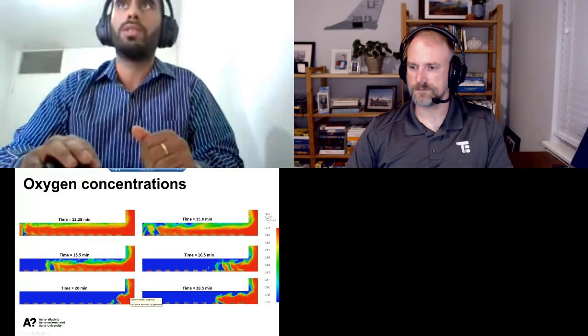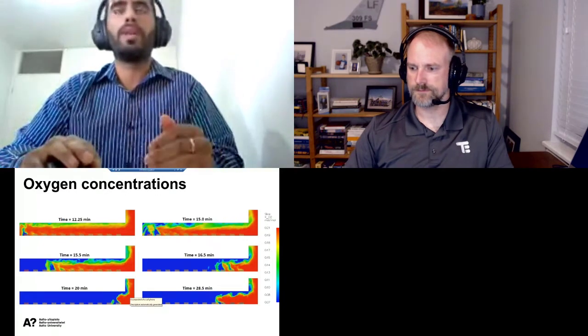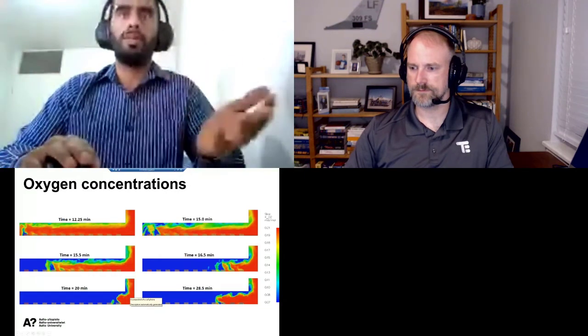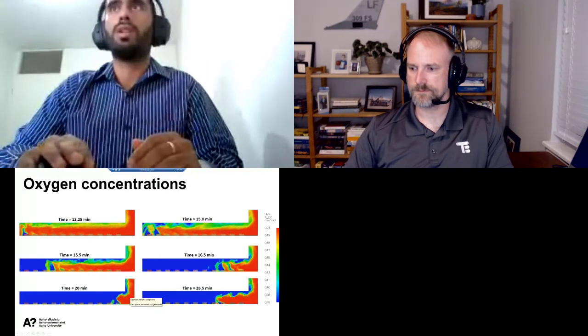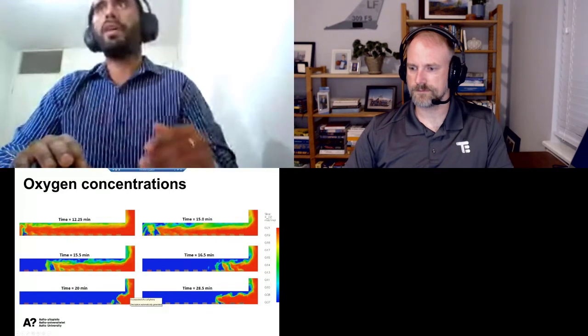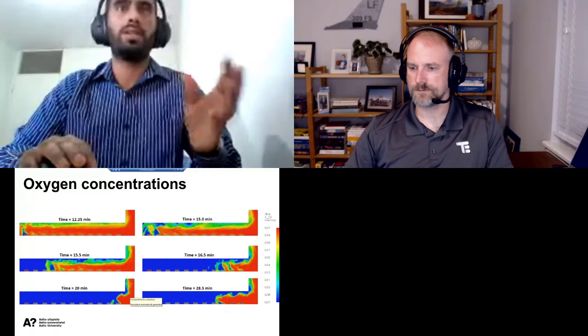In the second row, you can see a significant yellow near the crib. That is due to the moisture evaporating. What the ceiling flow and the radiation from the flames do is evaporate the moisture from the cribs along the other rows, and that prepares the cribs for the rapid propagation when the oxygen suddenly reduces.